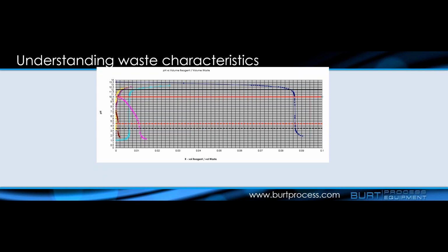There are buffers that work at really almost any pH, and an interesting thing, buffers are actually utilized to calibrate pH instrumentation. They're generally 3, 6, 9, 12 buffers, which are utilized when you're calibrating your pH probes for maintenance as part of a pH adjustment system.